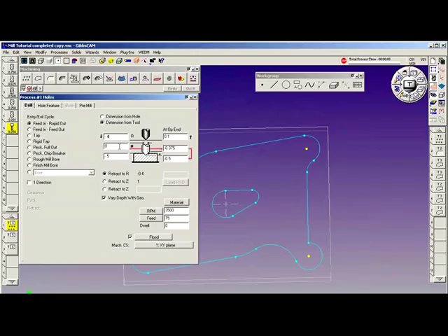And I want a chamfer diameter of 0.215. Break the edge at the top of the hole. What size is my cutter? Okay, we'll just make a hole. Yeah, 0.215. That's fine. Retract to Z 1 inch.